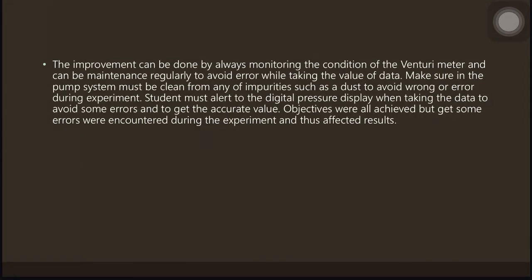The improvement can be done by always monitoring the condition of the venturimeter and maintaining it regularly to avoid error while taking the value of data. Make sure the pump system is clean from any impurities such as dust to avoid wrong readings or error during the experiment. Students must be alert to the digital pressure display when taking the data to avoid errors and to get the accurate value.